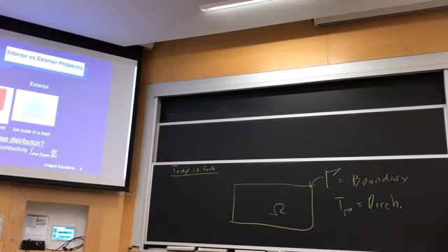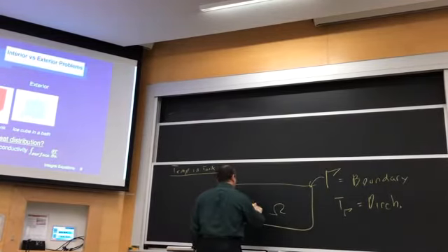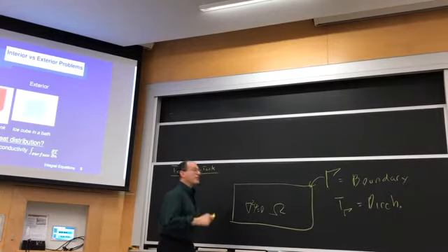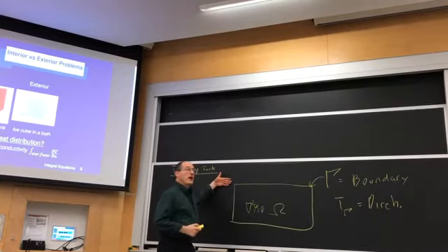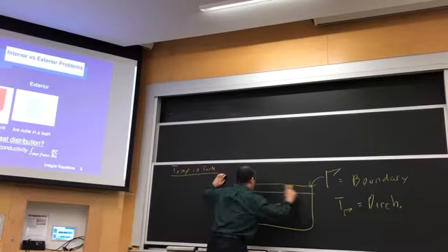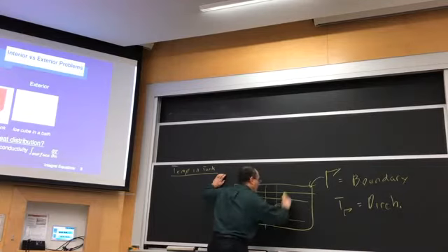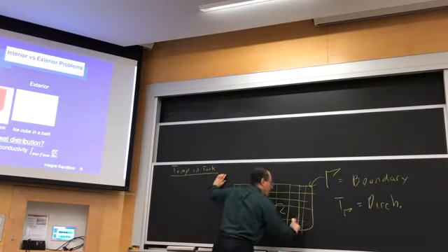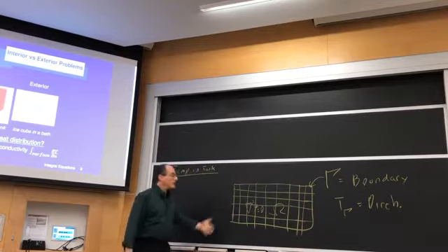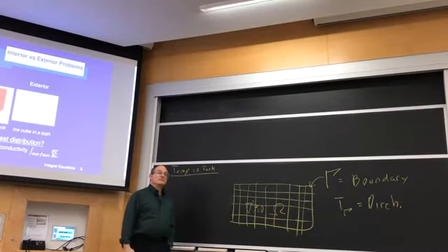How do we figure out what the heat flow is? Suppose I have in omega, the Laplacian of some potential is equal to 0, and I have some thermal conductivity. How do I figure out what the heat flow is into this tank if I'm using finite difference methods? Well, the first thing is you set up a grid, or use finite element methods. Then how do you figure out what the heat flow is once you've set that up? You're going to need the normal derivative of the temperature at the surface. How will you get it?